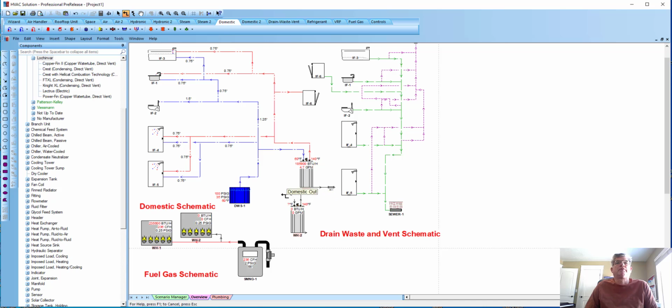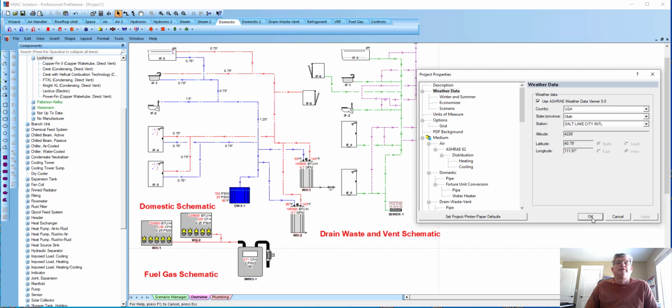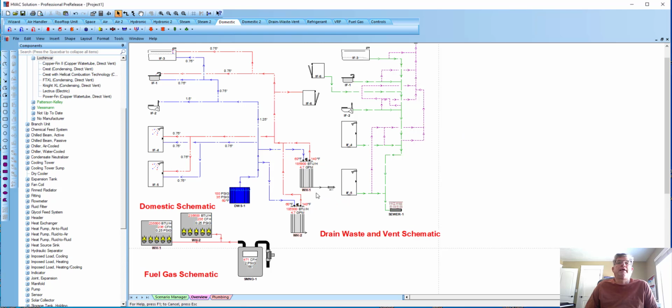So there's my supply. We'll turn that over and connect it right into the hot water supply, and then the domestic from a tank, some source. If all goes well, you'll see the two boilers are now 185,000 BTUs. The load down here is a little bit higher because of my altitude. If I double left click on the white screen, I'll see my weather data, where I'm located, the elevation. So we adjust that water heater selection for the efficiency it has, as well as derate it for the elevation.